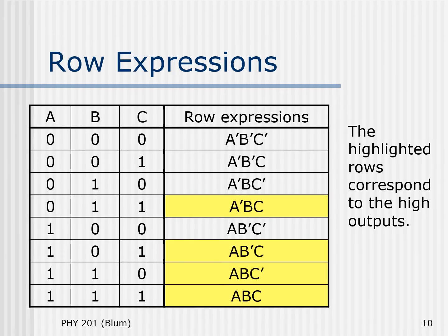So shown here is a 3-input truth table. A, B, and C are the inputs, and we have all 8 possibilities, from 0, 0, 0 to 1, 1, 1. And we've written down the expression for each individual row. The expression would be a 1 for its given row and 0 for all other rows.